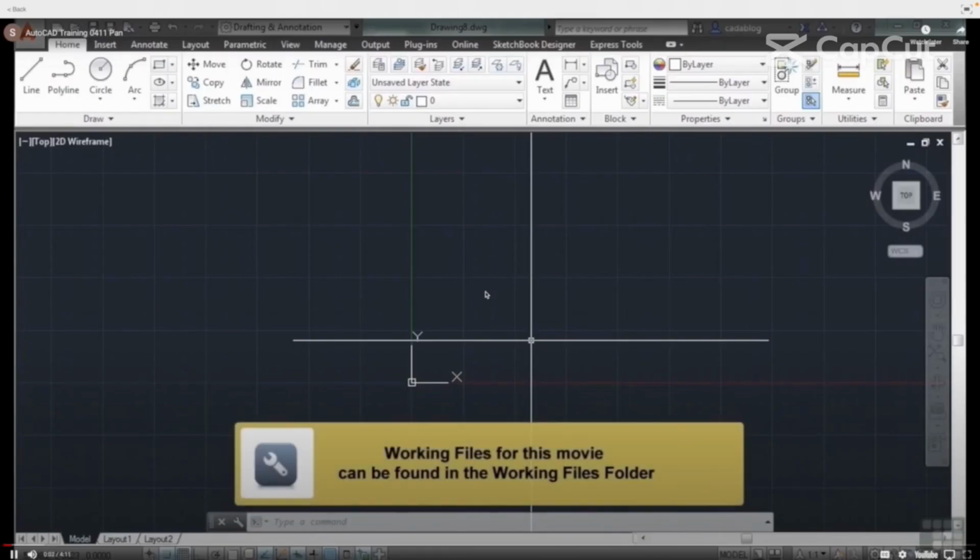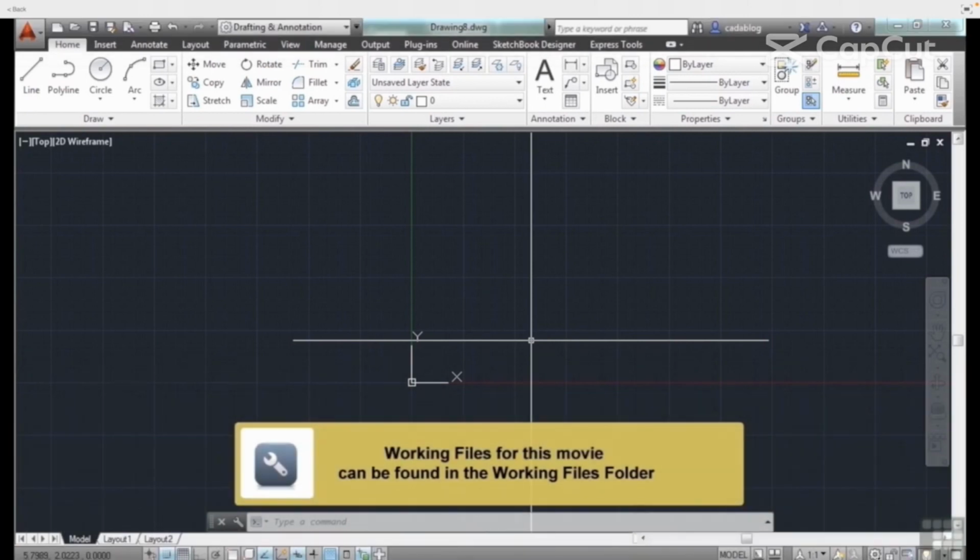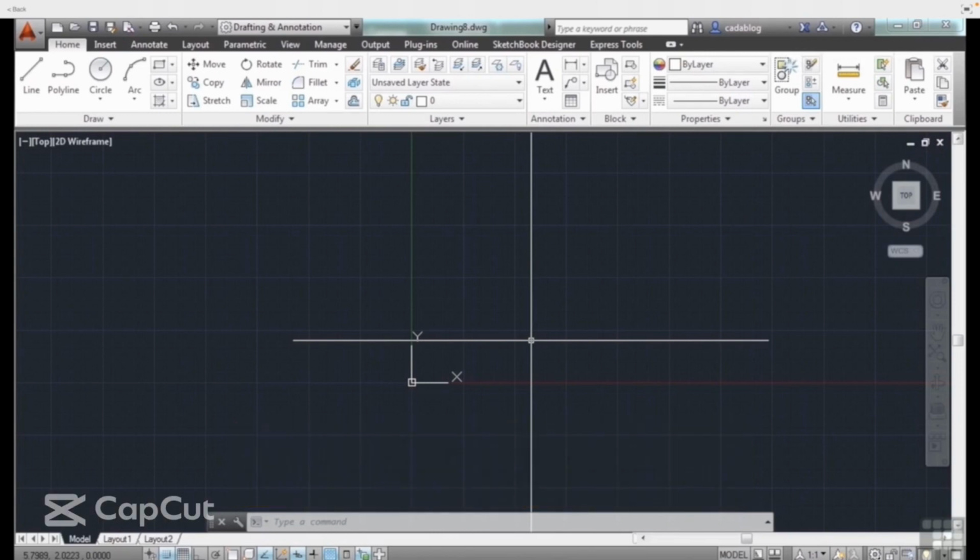If you have more than one object in your drawing, and trust me, you're going to, you will find that you need to navigate within your drawing. One way to get back and forth in your drawing is to use the pan command. Panning is not that difficult, not anymore. For many releases, we have had real-time panning. That means that you can see where you're panning and the screen moves along with it.